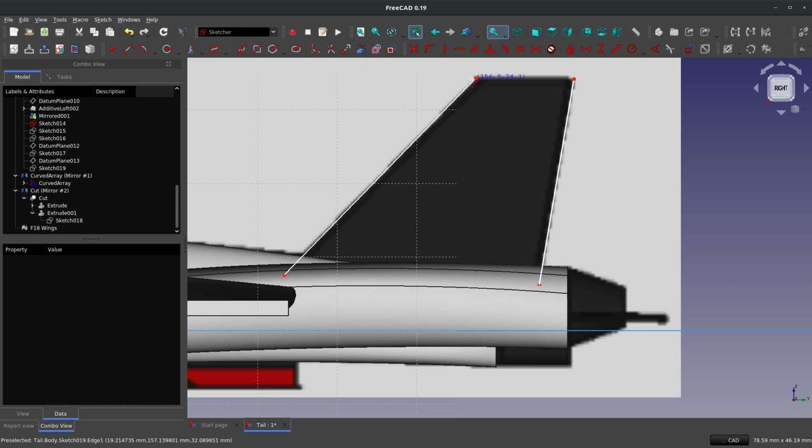I was acting like I had polyline on. Clearly I didn't. So that looks like it's held pretty tight. Now I'm going to close this up. If I like where these are sitting, I'll simply lock these points in place, and then make sure that these lines are within my body. Since this is simple tracing and I've got this kind of funky NURBS surface going on, I may have to adjust this after I extrude if I have an edge coming out of my body. But this is looking pretty good.